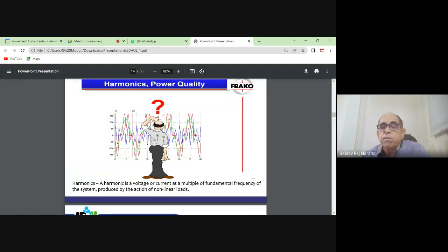So it becomes a very important thing, particularly for energy management professionals. They have to see now the kVA reduction. The kWh reduction is a thing of the past now. Earlier we used to put systems just to reduce the losses, but the payback doesn't come with just minor losses. The reactive power system hardly generates ROI for payback of the active power losses.